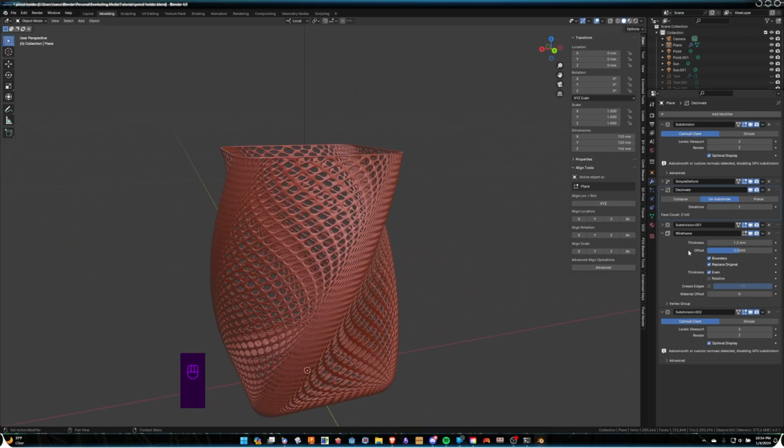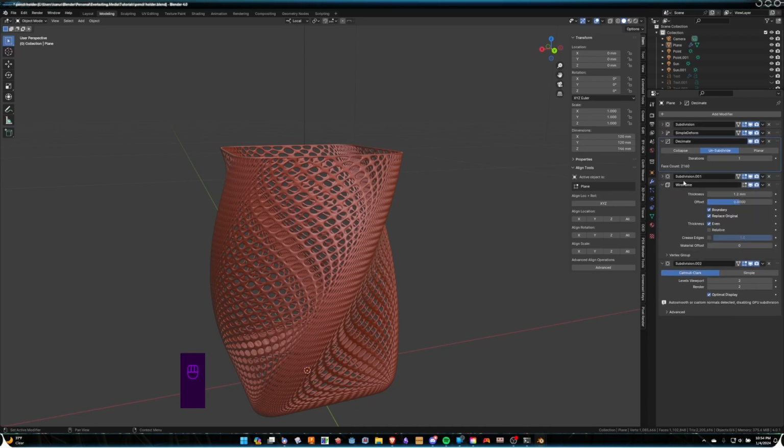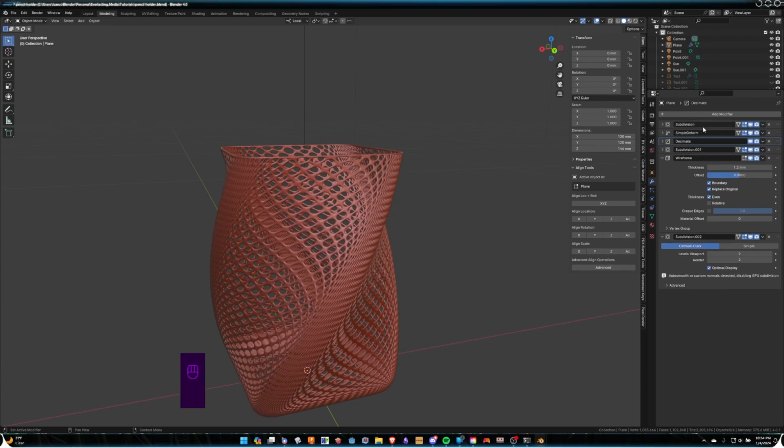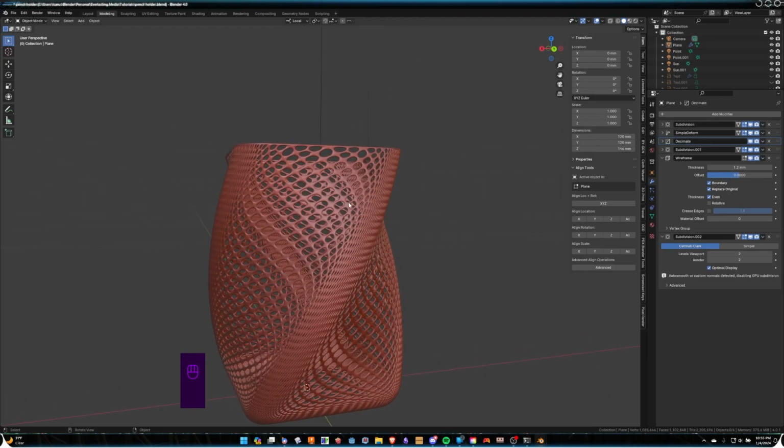Now, sometimes if you have a wider mesh, it's better because you have more vertical layers that can stack and less overhangs that your printer has to deal with. And you also should be reminded that your printer will end up making quite a bit of noise when it's going back and forth in all these holes. It tends to be a little hard on printers, especially if you try to print these types of things fast. It's normally better to print them at stock Prusa speeds or slower even. And then you get better overhangs.